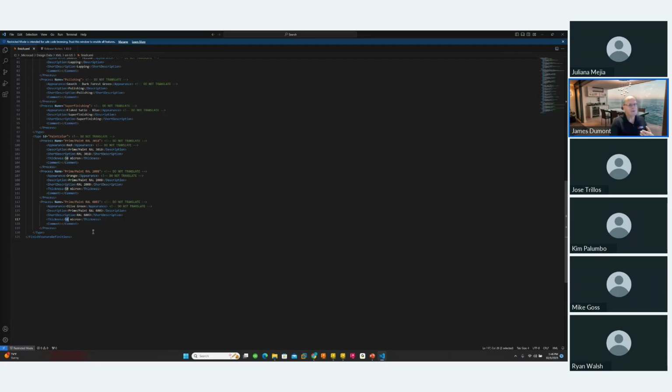We know the job processor by default is every 10 minutes. Everyone says, well, how do I change that? Well, you have to go to web.config. You have to find it in that little config file, which is like an XML, and change it there. It would be really nice if you could have a better interface to make the changes in the software. So Autodesk is working on that. I can't say any more than that, but they are working on it.